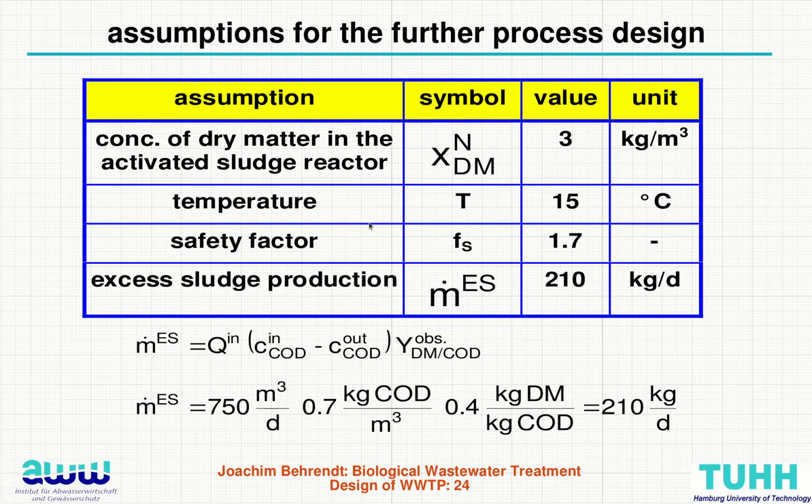Because we have a small wastewater treatment plant, we have a quite high safety factor. Now in the new regulation this is the process factor, but the safety factor was in the range of 1.2 until 1.7 depending on the size. Hamburg wastewater treatment has a 5,000 kilometer sewerage system, and there the water is coming more or less uniform, and they have the safety factor of 1.2. But here we have a small settlement or something like this, so there we can use it a little bit higher.